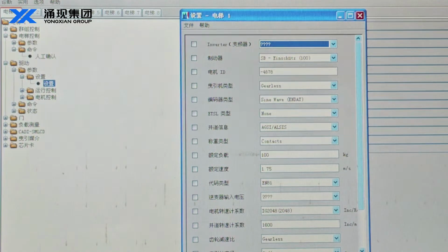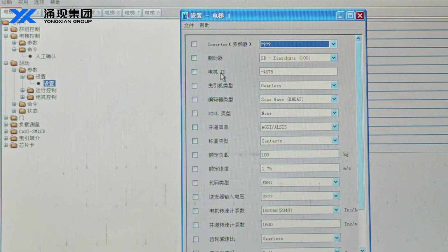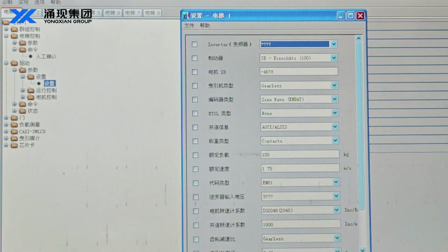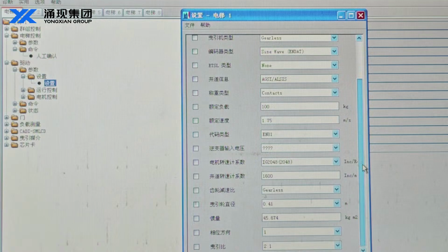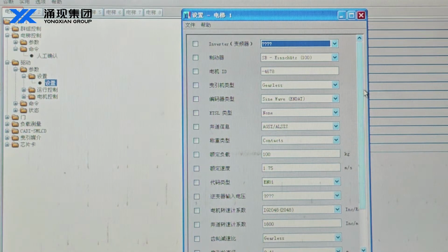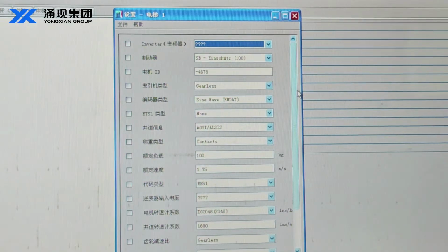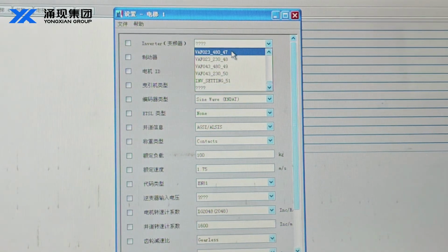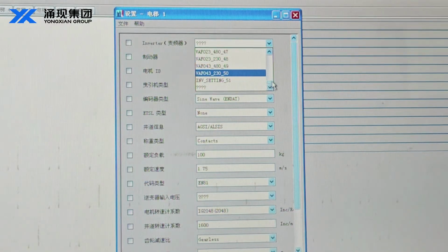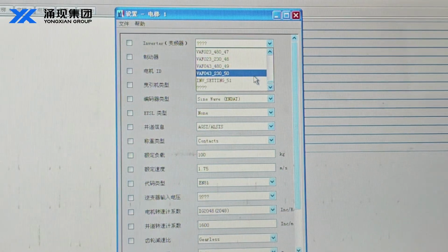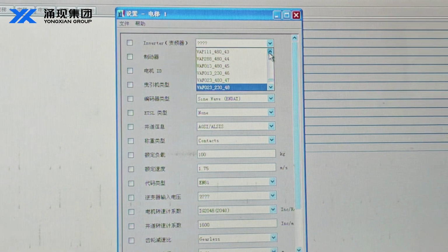然后刚好我们在这里面就发现，这款里面有我们的变频器，包括我们的制动器、我们的电机、包括电机类型。平时我们更换完变频器，包括我们的曳引机替换以后，要进行修改的参数，包括我们的电梯的速度，都在这里面进行修改。Yeah, here is the traction machine type, the driver type, and even the speed of the elevator. For example, if you change a new inverter, let's say you change VF33BR to VAB33. After you change the new inverter, you have to set that in the drive part.